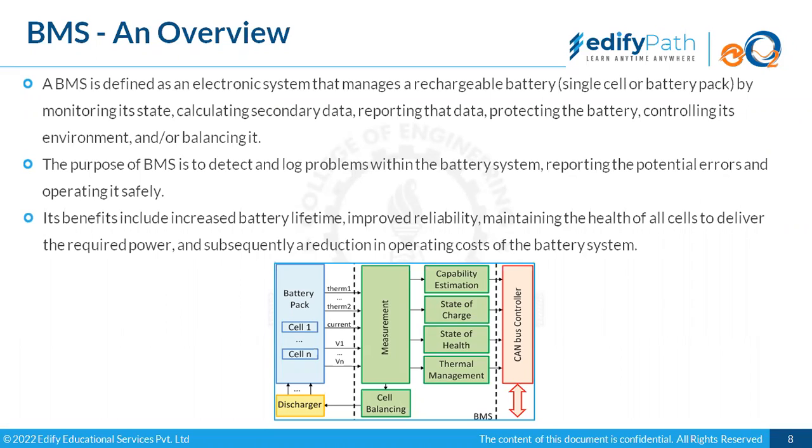And cell balancing, as we discussed: if some cells are holding more voltage than other cells, that voltage would be automatically drained out by the BMS so that all cells are at the same voltage. An ideal battery is one in which every cell discharges at the same rate and charges at the same rate. Then the utilization and performance of the battery would be the best.